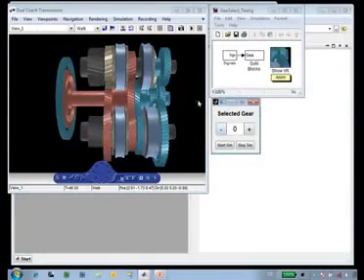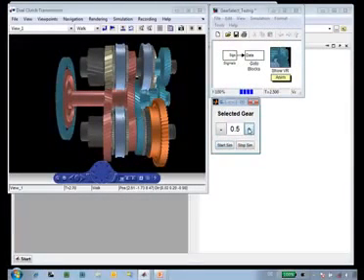Here is the model that we used to test the animation. This simulation is controlled using this GUI developed in MATLAB. I'll start the simulation and then use these buttons to shift between the gears. As I shift to a half gear, a dog clutch will engage the next gear to which the transmission will shift. As I shift to a full gear, you can see that the input clutches will change state, again controlling the next gear to which the transmission shifts.